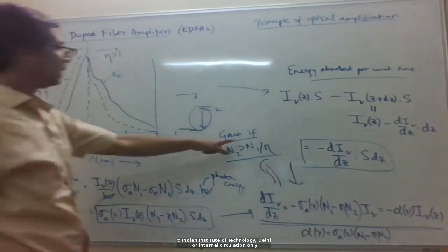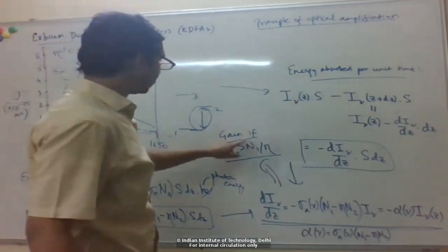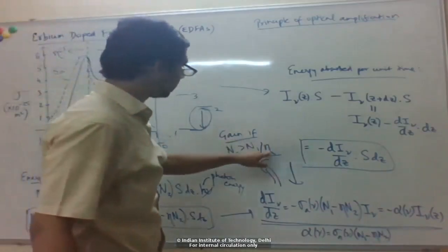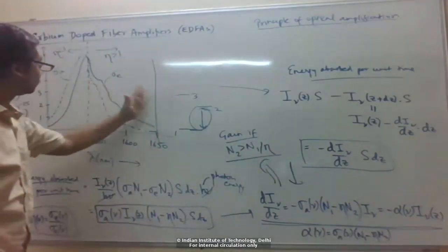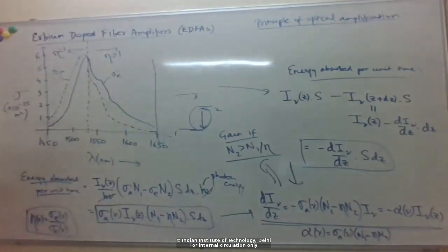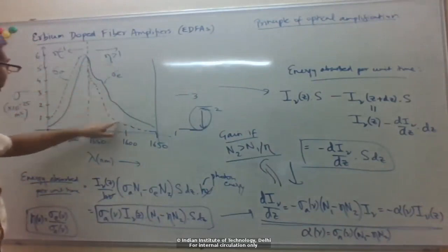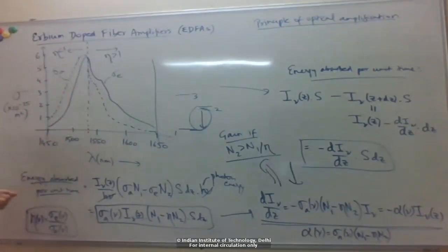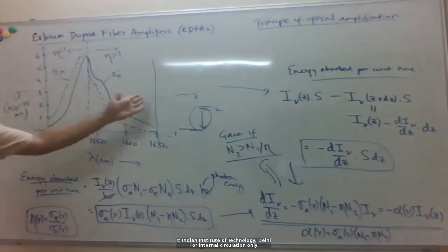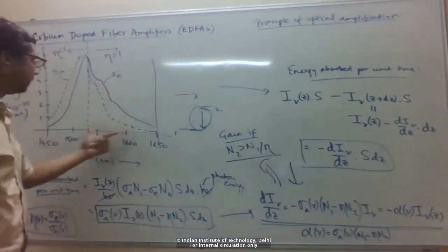And you can see the condition for gain is easier to achieve the larger eta is. So these wavelengths are amplified more easily, and for the longer wavelengths, this eta ratio is larger, so the longer wavelengths amplify first before the lower wavelengths. Below 1530 it's difficult to get amplification at all. So that's why EDFAs work from 1530 to 1610, in this range.